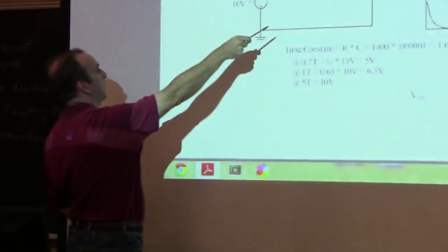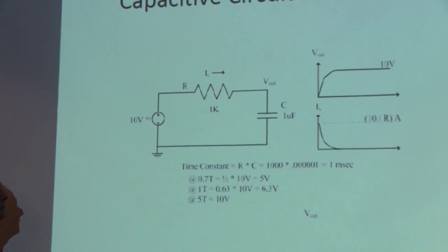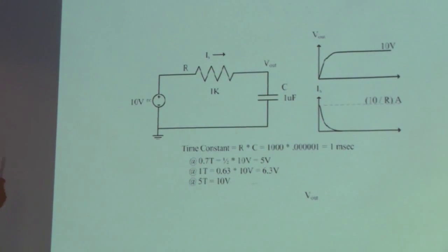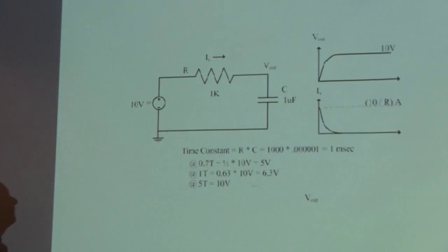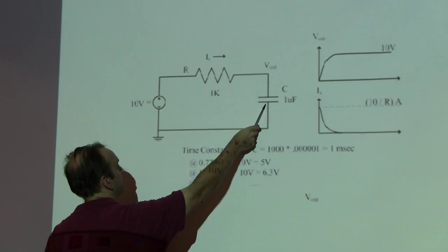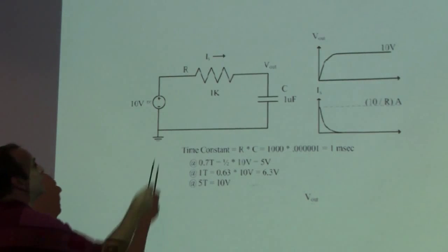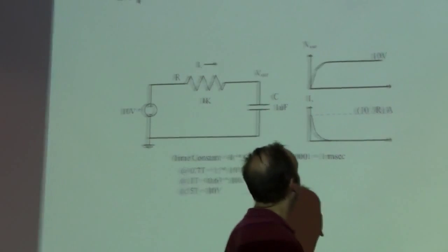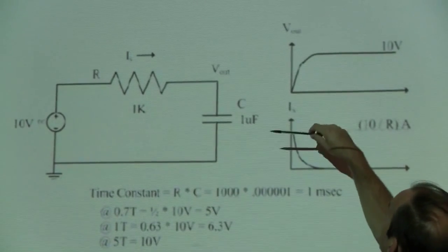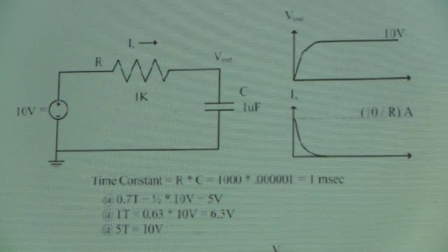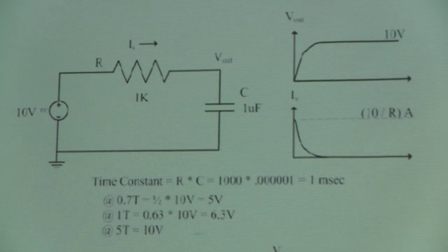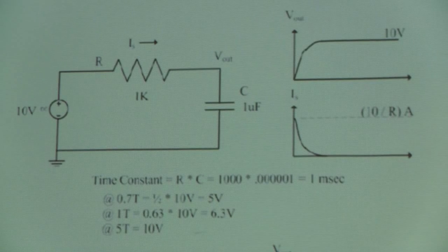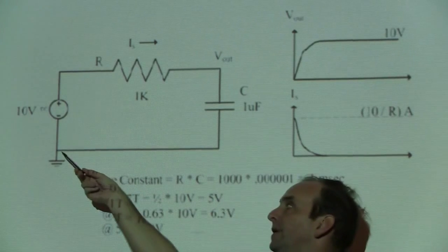So when we look at a circuit that has a reactive element, i.e. an energy storing element, there's a couple different ways to look at it. One of the first ways is as a transient. The transient response says, this little guy at time 0 has no charge on it, therefore its voltage is 0. And I turn this 10-volt DC power supply on. So what happened to it? Well, I didn't want to go into all the math, but there are two curves being traced simultaneously. This is the voltage, this is the current. To give you a little bit of the math, the current through a capacitor is C dV/dt. In other words, the capacitive value times the first derivative of the voltage. I just created a large derivative because I just turned this thing on.